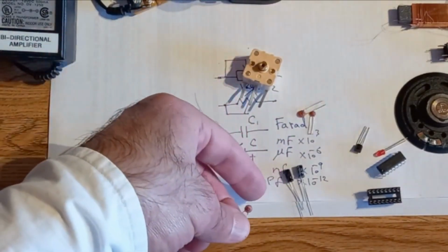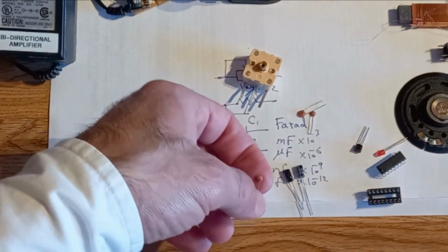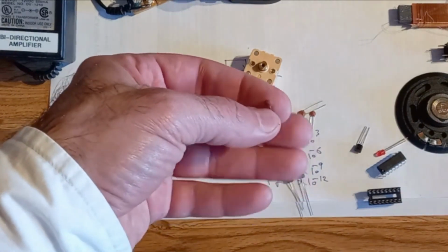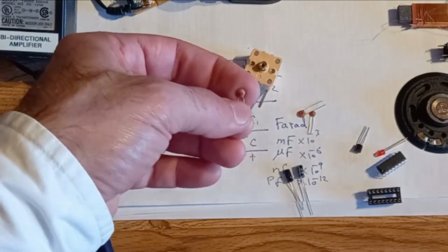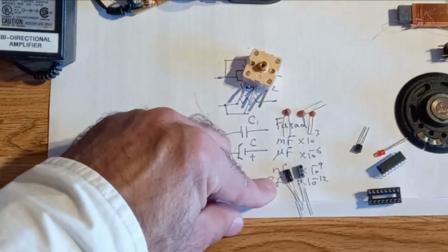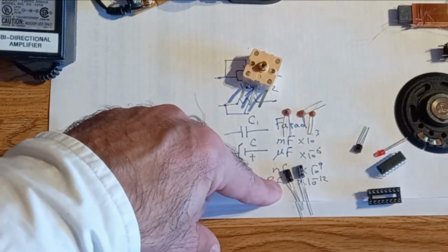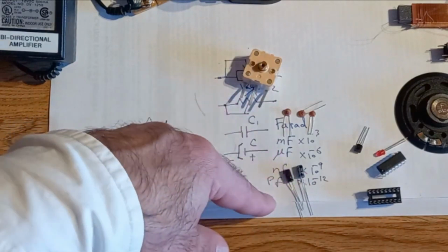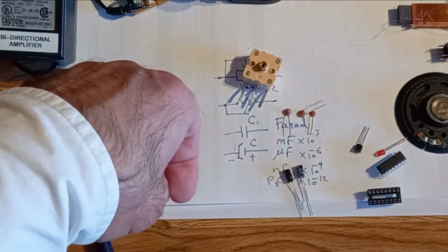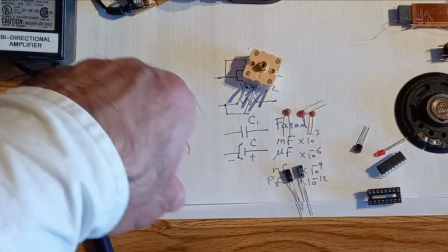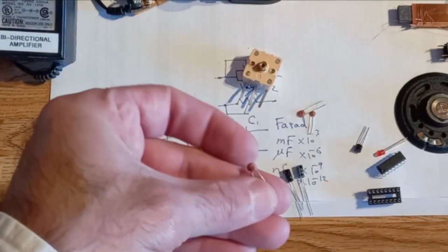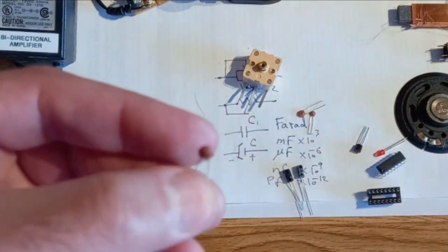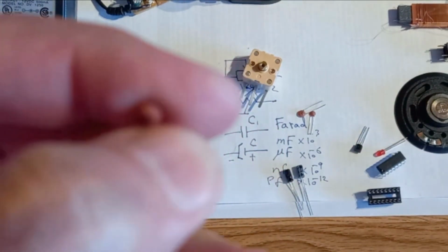And the value of the capacitors, either electrolytic ones or non-electrolytic, the non-polarized ones like these ceramic ones, are all written on them. But when it's electrolytic or polarized, they actually write the unit. So for instance, the one I showed you is 0.47 microfarad, it actually spells it out, microfarad. But with the case of these ceramic capacitors, in this case, for instance, it says 223.